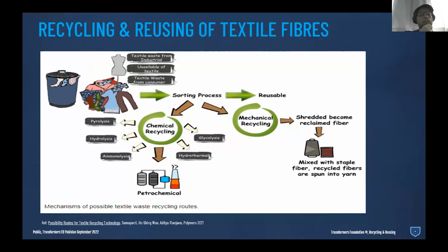One thing important to tell you is that on post-consumer, mechanically recycled waste, there's only one option. There's only one time, once, that you can recycle. The idea that this is a kind of permanent loop, so you keep using, this is wrong. The only way to recycle on and on the same thing is chemically. We go back to raw materials, we reuse them. Mechanically speaking, everything depends on the length of the fiber and the mechanical features of the fiber.